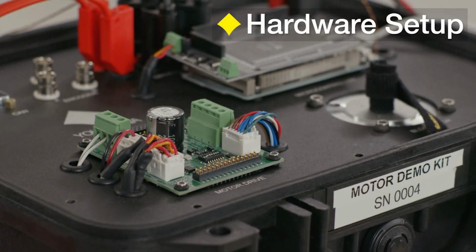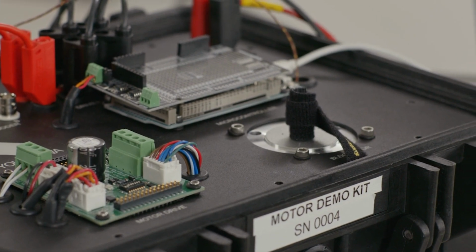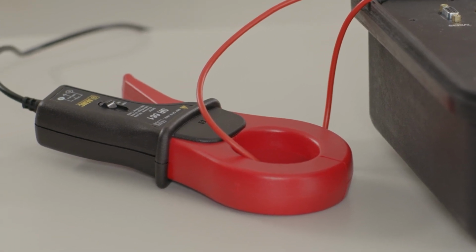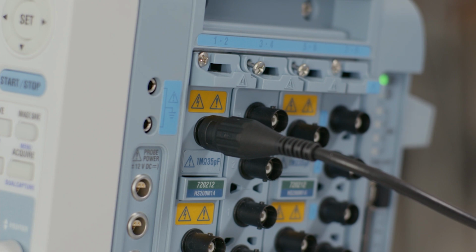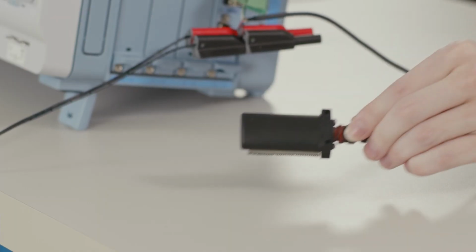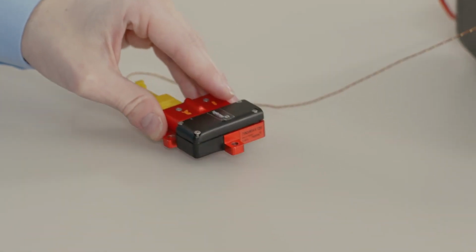Our demonstration today uses the output of this motor drive, which is then connected to a 3-phase brushless motor. The current output of this drive will go through a current clamp to the input of our ScopeCorder on channel 1. We'll also be monitoring the temperature of the motor using this wireless thermocouple amplifier from Texense with a K-type thermocouple. The wireless receiver for this sensor will connect to the CAN input of the DL950.